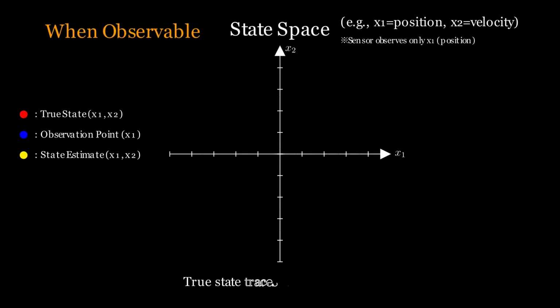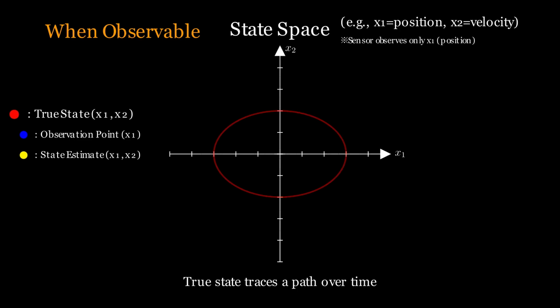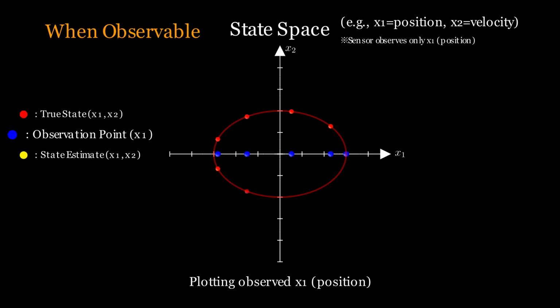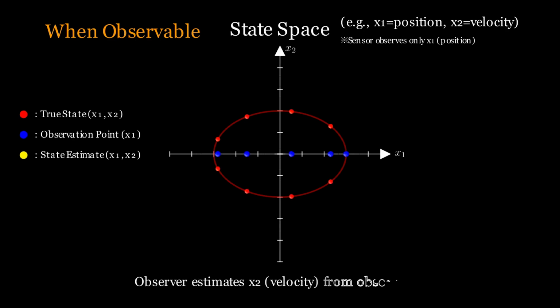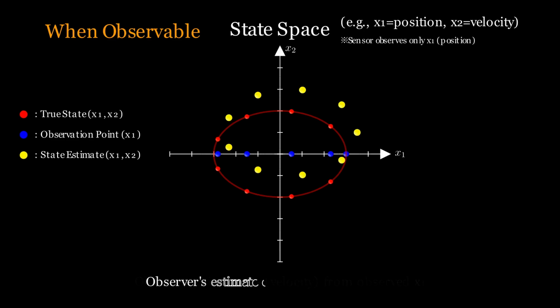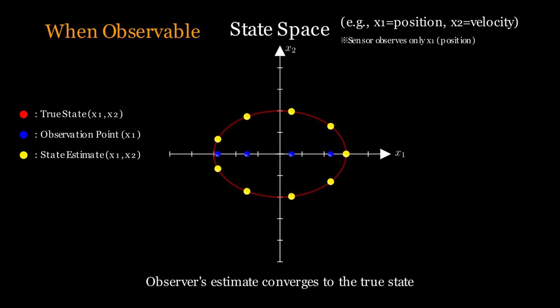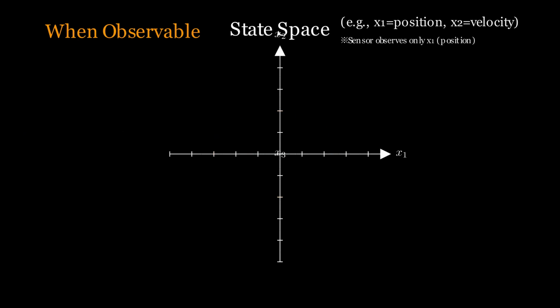Yes, it corresponds to the question of whether you can determine all joints and body velocities accurately from just IMU and joint encoder data. Since you can't directly measure all internal states with sensors, this becomes a necessary condition for constructing a state estimator called an observer to estimate unknown states from observable outputs. Lack of observability also suggests insufficient or poorly positioned sensors.